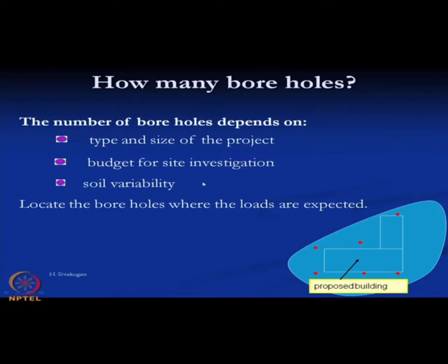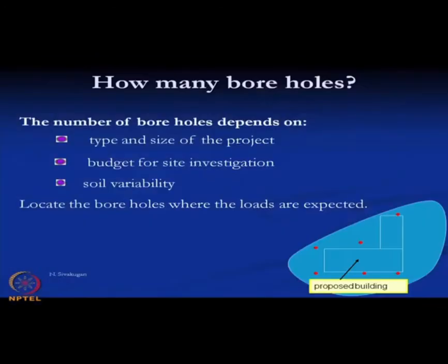And if the soil variability in different boreholes is very much, then we should increase the number of boreholes for a particular site. So, locate the boreholes where loads are expected.